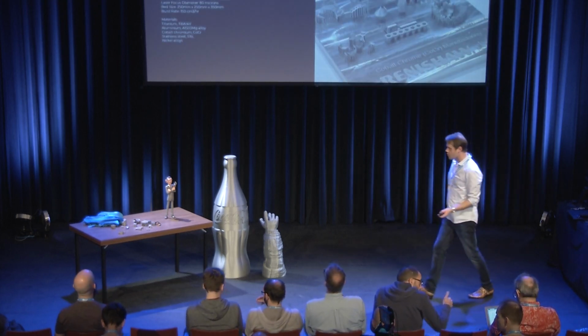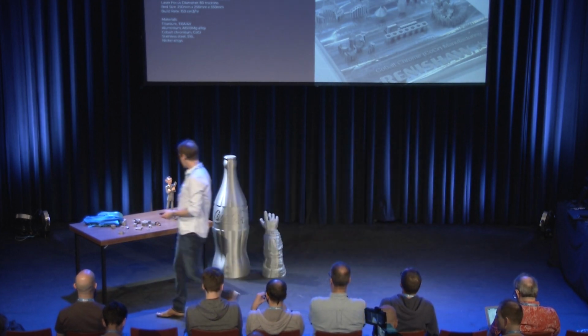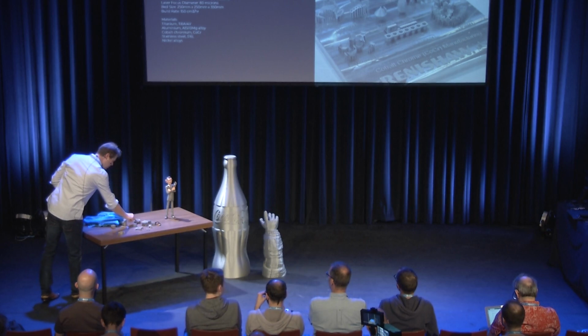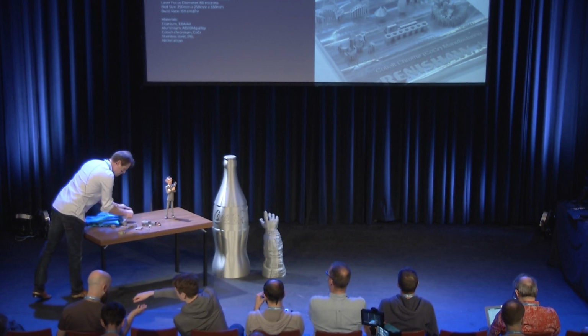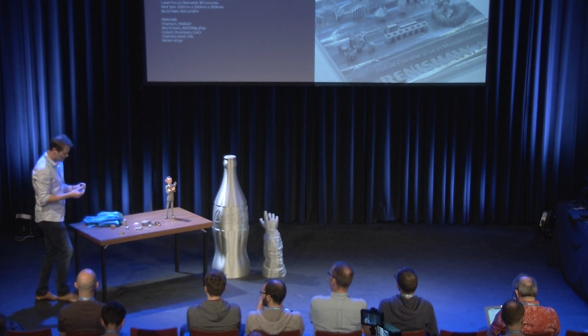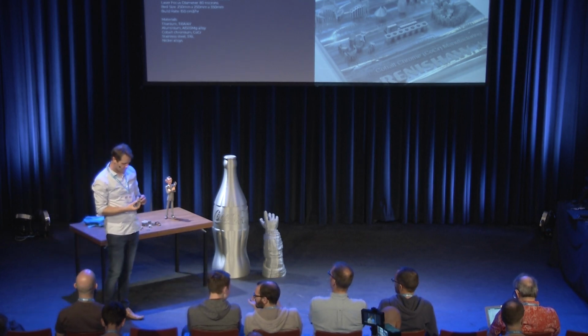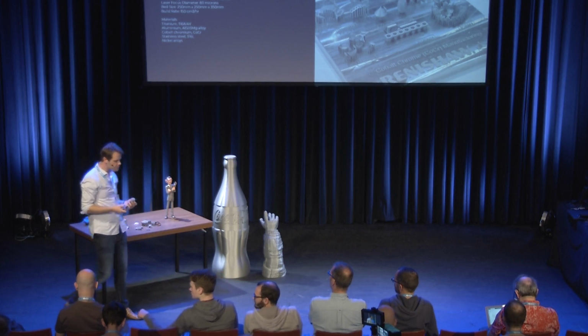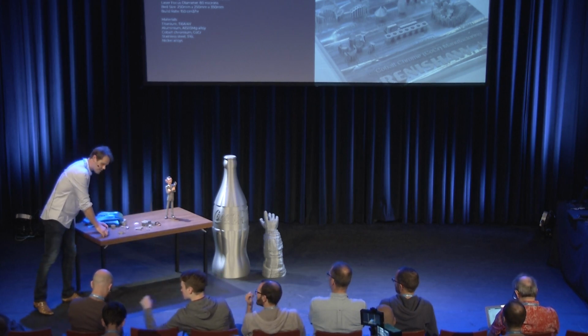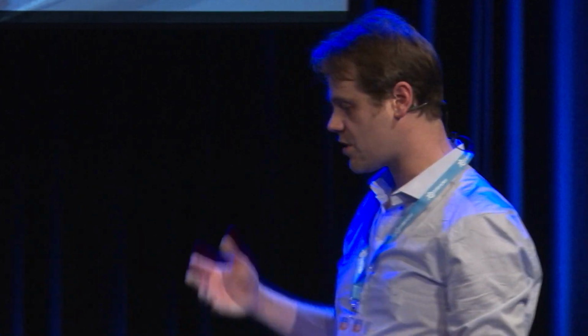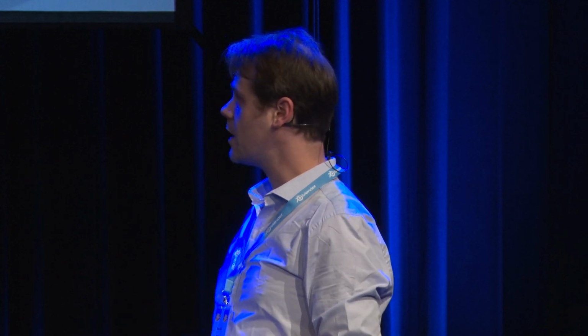Right, so even more, when we get to metal on a larger scale, we've got Renishaw. These guys produce models on quite a crazy scale. High resolution, not comparable to the smaller scale things, but at the end, please have a look. This uses a solid metal build plate. You've got an SLS system, so selective laser sintering. It can use up to 4 lasers at once on the same build plate, so it can work really quickly. I think you can produce an entire build plate in about 15 hours.